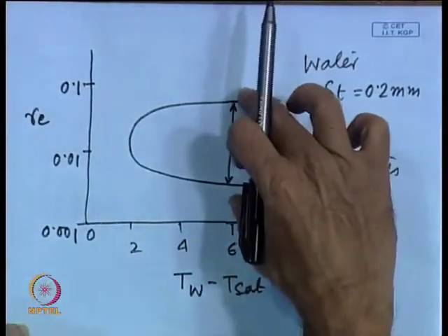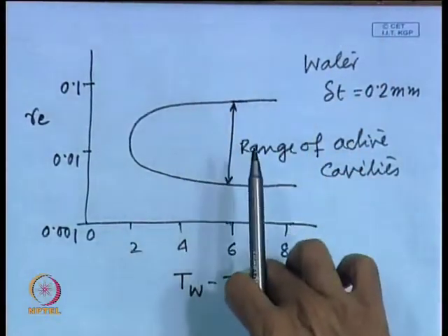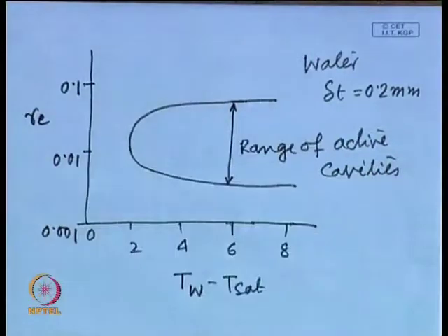So, this curve is flaring out. So, at a higher degree of superheat, a larger number of cavities will be activated. That is why we can relate it to our day to day experience, that as we increase the temperature, let us say on a container where boiling is taking place, we see more vapor bubble formation, because more cavities are getting activated.